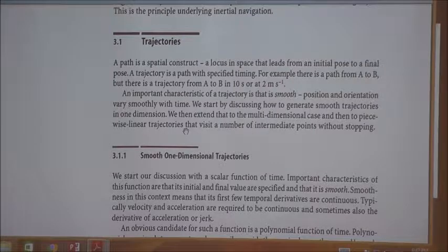As you saw in an earlier lecture, perhaps on day 1, week 1, the robot has to move from a point A to point B. And you recall that the robot, let's say, has 6 motors on the 6 joints. So you have 6 control systems. Each of them has its own reference, and they all have to be generated by a trajectory for that particular joint. So you have a set of trajectory generation for joint space, and then when the robot ends up in the real world, in Cartesian space, it's the Cartesian trajectory. All of that has to be done normally by some kind of piece of code.